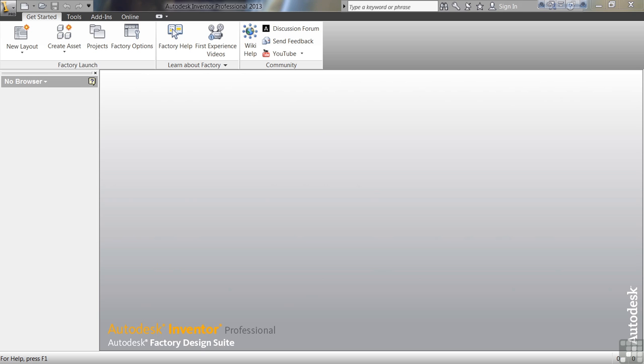This also helps you capture the design intent. A parametric sketch consists of 2D geometry in which constraints are applied to control the size and potential behavior of the 2D geometry. There are two different types of constraints: geometric constraints and dimensional constraints. As you create geometry in Autodesk Inventor, some geometric constraints are automatically applied.